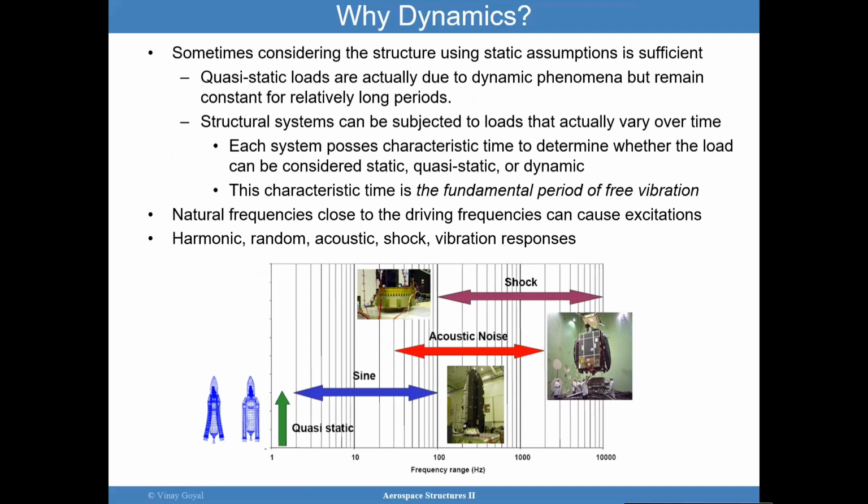Structural systems can be subjected to loads that actually vary over time. You're going to have these structural systems where loads are acting on them. What is important to understand is that there are situations where the loading is very slow, and so it doesn't cause any dynamics or vibrations. Each system really possesses characteristic times that will help you determine whether the load that you're applying should be considered static, quasi-static, or dynamic.